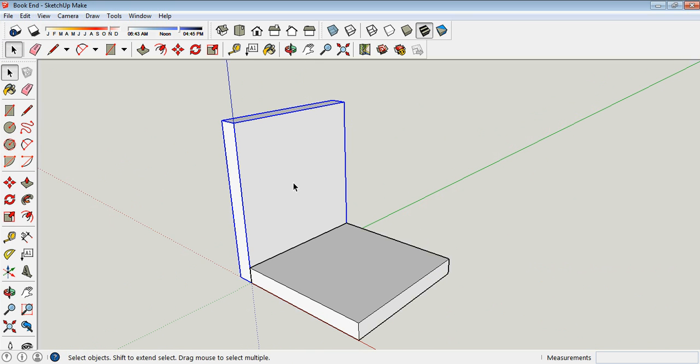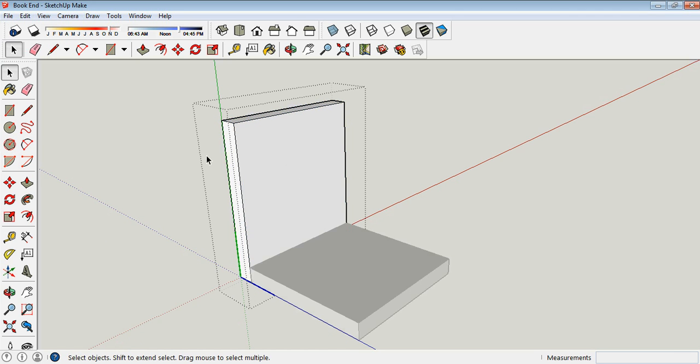Now, to make changes to the bookend, you can use some other functions, such as the arc, or the pencil line tool. We make use of the arc tool on the left hand side. Right, so we do a bit of basic changes. Now, because it's a component, we need to double click to edit it. Alright, select the arc tool. When I go to the center of the line, it turns blue. I click on it. On top, I can also go to the center.